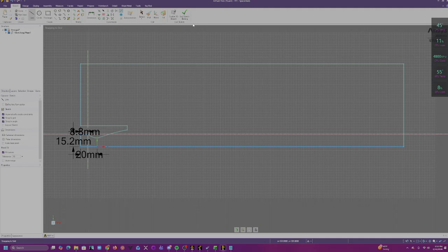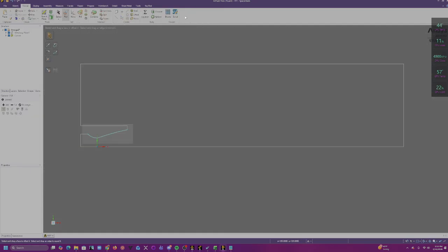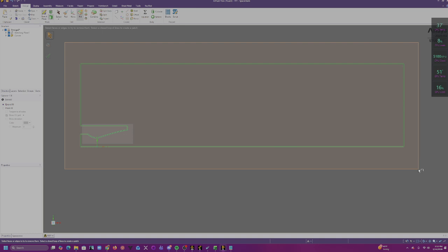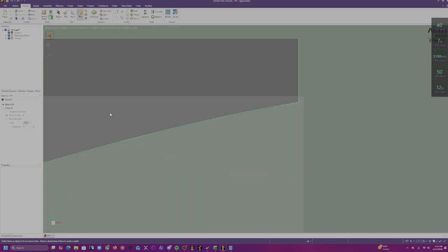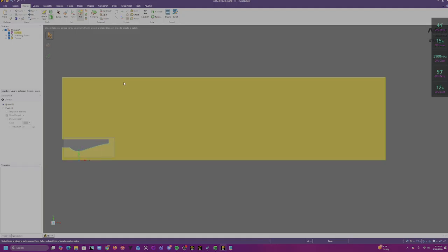Okay, so next step, what we can do is end sketch editing. Once we have our enclosure, we can end the sketch. Go ahead and end sketch. Now what we want to do is fill. So go ahead and fill, and then click and drag throughout the entire surface, right? So click and drag, it should look all green. So all of these lines should be all green. After that, you want to click the check mark, and it should make a nice surface, right?